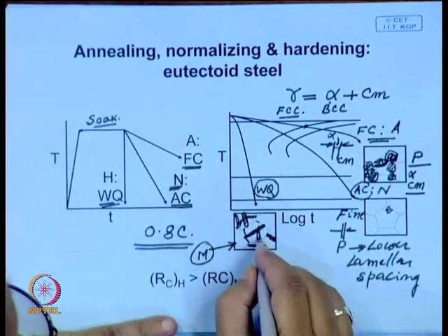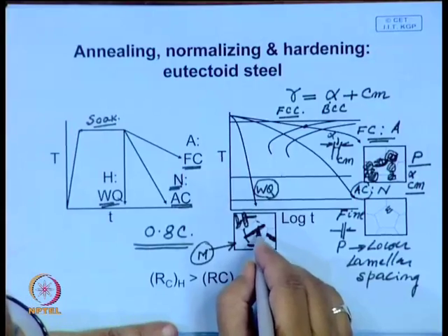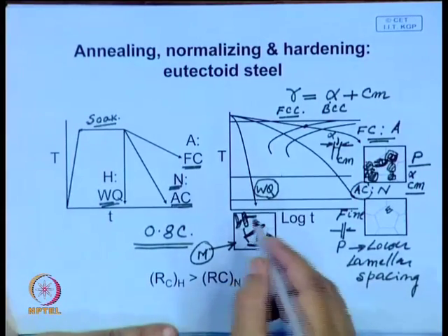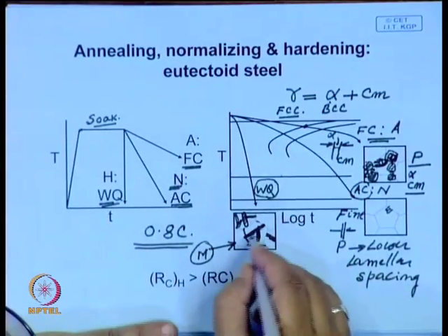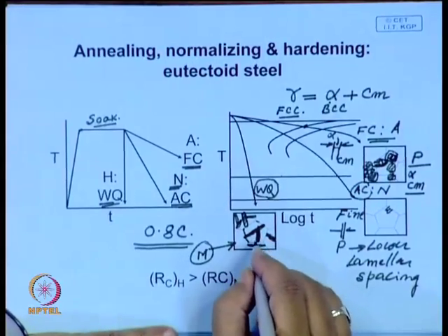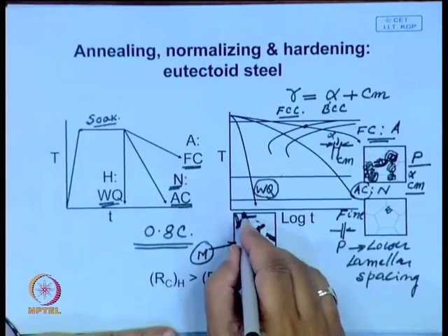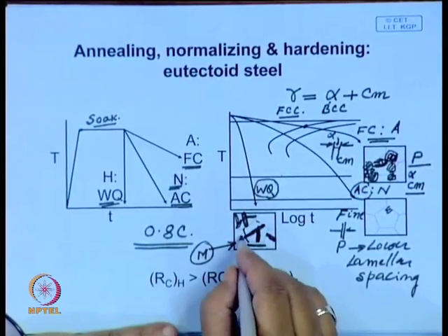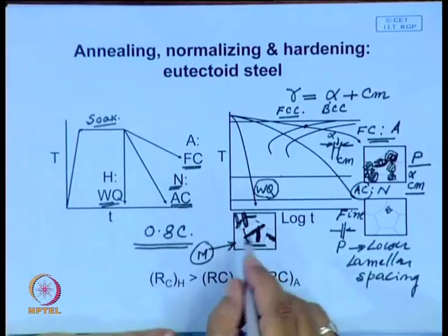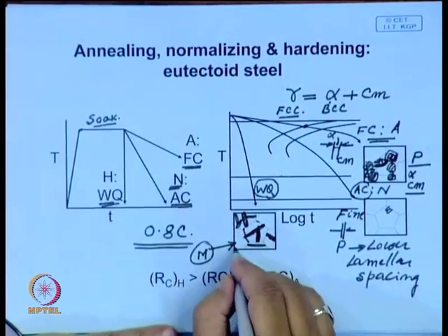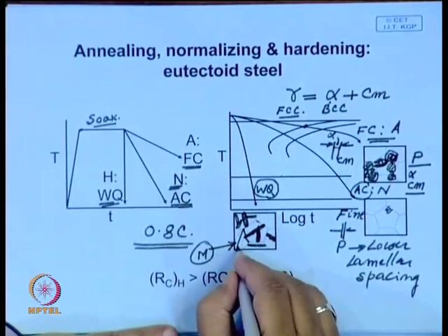There is deformation in the lattice, which makes this steel very hard, and also since carbon atoms are kept by force in solution, this also gives a substantial amount of solid solution strengthening.